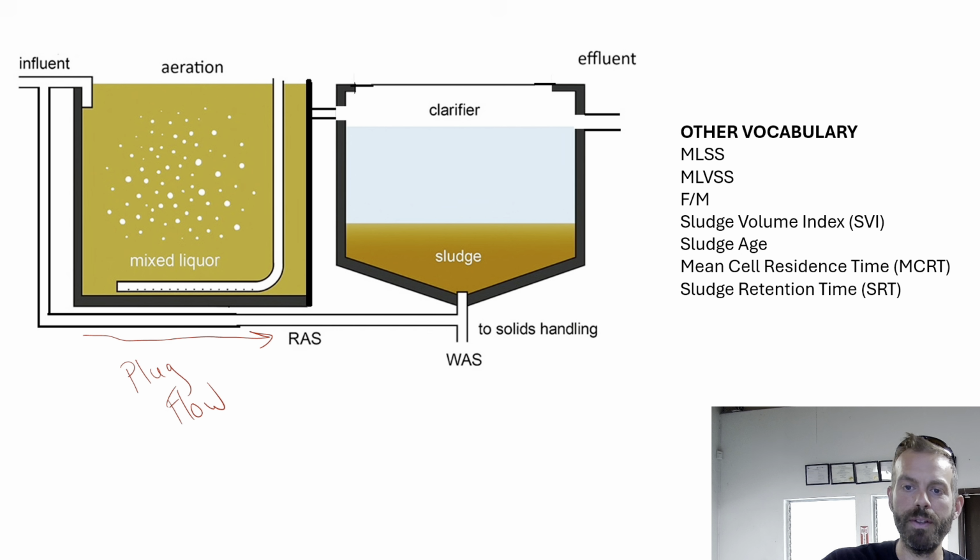So you notice there's a clarifier here. This takes the place of my membrane chamber, okay? I have a membrane bioreactor. In my plant, we extract the water off the floc and get a really clear effluent. We call it permeate. And in a clarifier, there's liquid-solid separation, and the floc forms and drags everything down, and then you get this clear effluent on the top. We'll talk about that in a second.